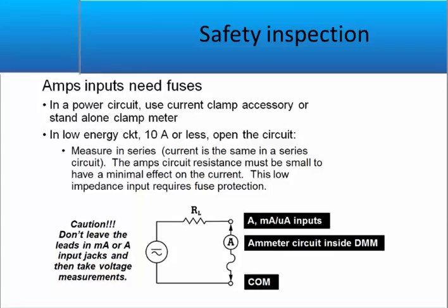Measuring the voltage of a circuit relies on the instrument, the multimeter for instance, being very high impedance, whereas measuring a current within a system requires a very low impedance. You don't want to put any extra load or resistance in series with the actual current, so you need to make the impedance within the meter as low as possible.